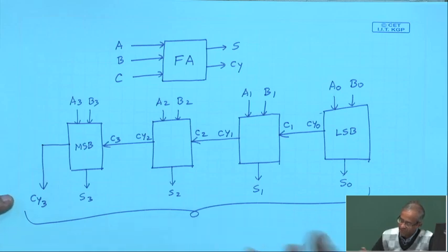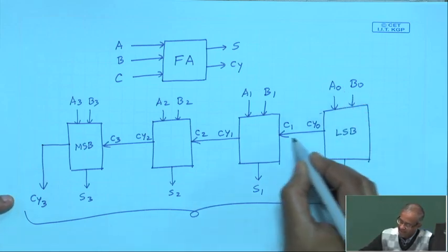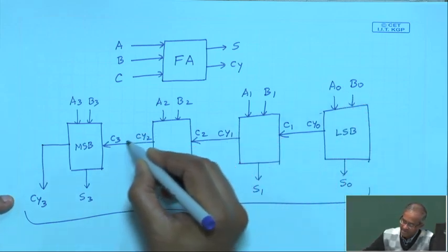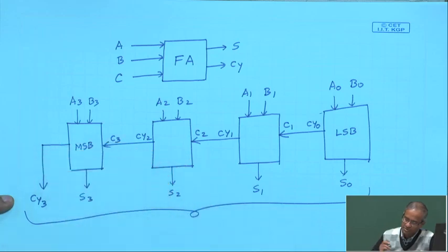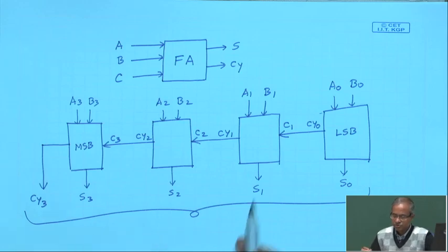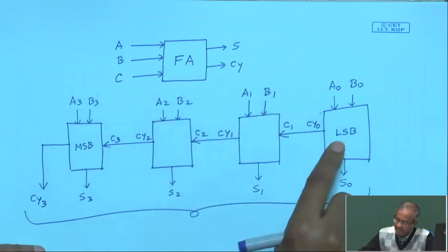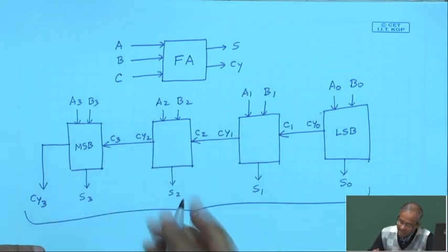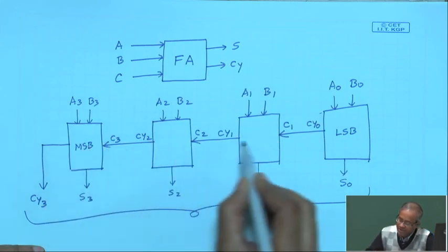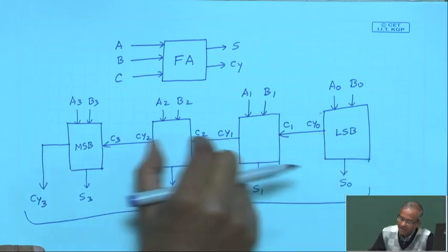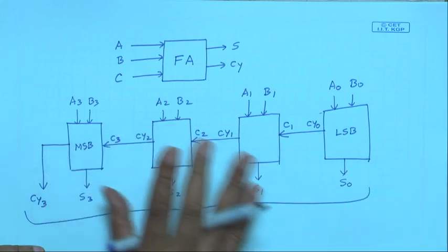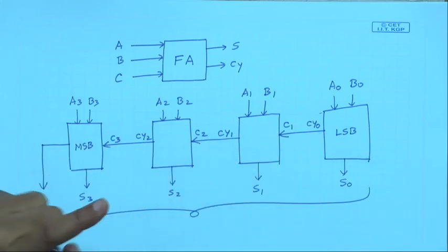This is called a ripple carry adder because the carry might ripple through the various stages before it comes out, right. So, you can see this was my behavior and this is a structural level description where I used full adders as the basic building block and I have interconnected them, right. This is just an example, I shall show this on the slide also.